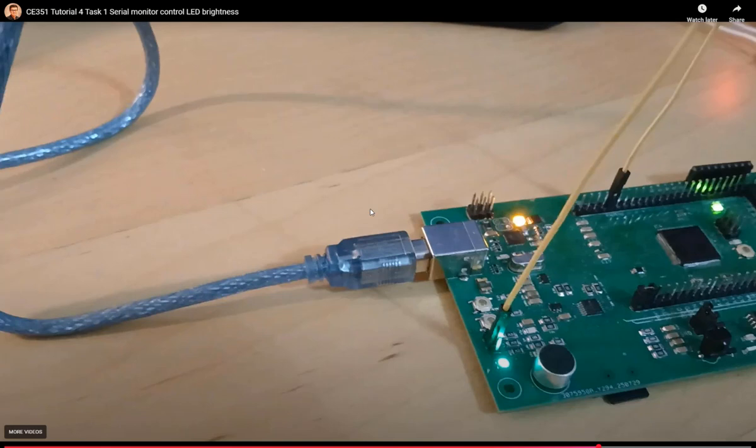So what I'm doing is I'm typing a command into the serial monitor, and whenever the microcontroller receives that letter or command, it is able to reduce the duty cycle of the PWM, which is making it narrower, and eventually the output power will be decreased as well. So eventually it's dimming that LED. Right? And you can also enter a different letter to increase the duty cycle of the PWM, or increase the width of the pulses, eventually to make it brighter. Okay, so that's how you control it through the serial monitor.